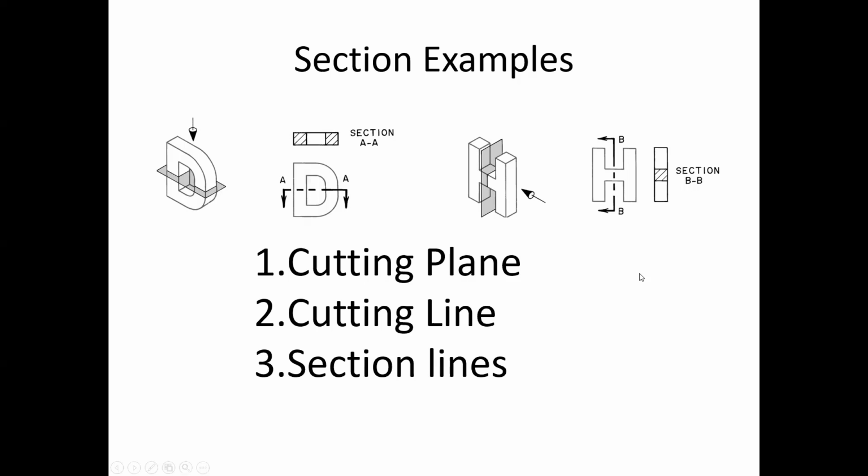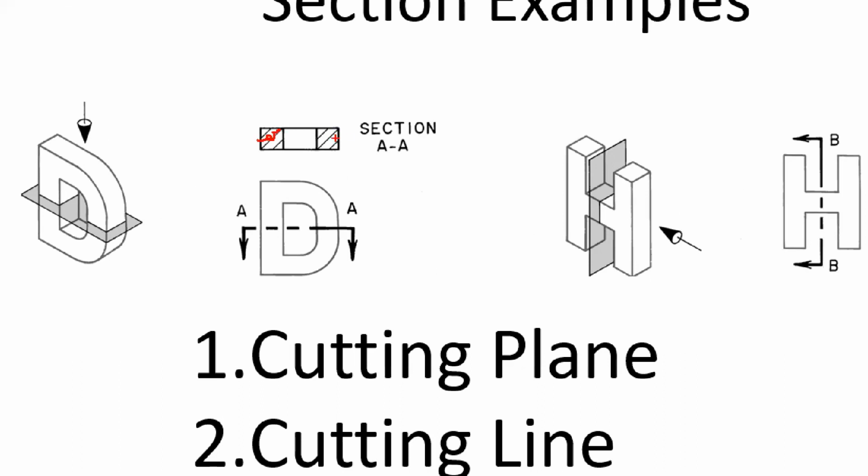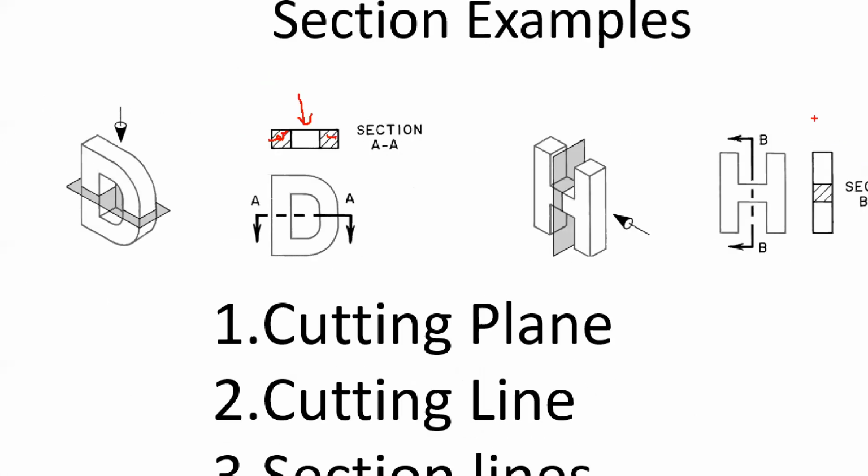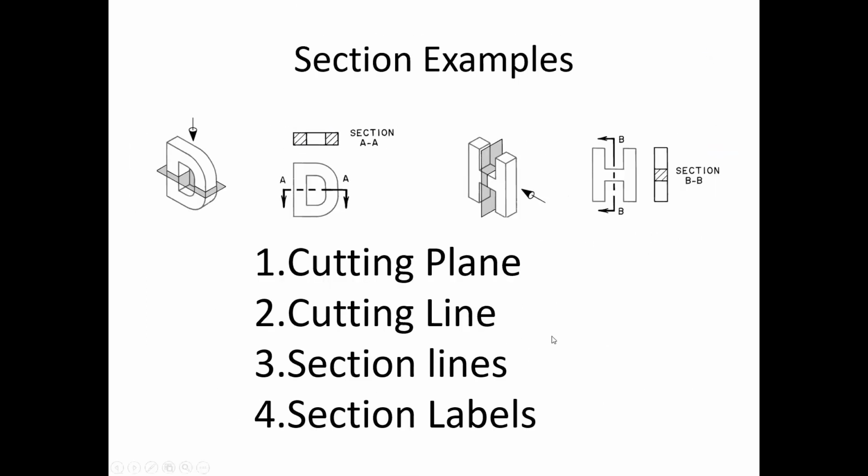represented by a plane. The section lines are where the material is actually cut, right? The cross hatch. Okay, they call it hatch. So we hatch in where the material really is, right? And where there's no material, we don't have any hatch. Same thing over here, right? No hatch here, no hatch here, hatch here. That's normal, right? Inventor can do that great if you don't have to do any convention stuff.